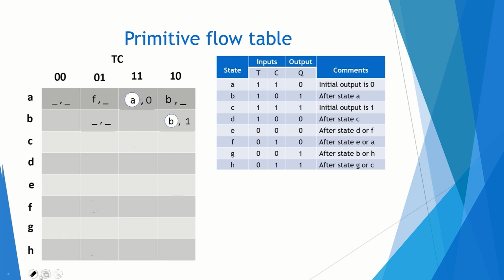So you can put dash here. So let us now see this B, that is 1 0, output 1. When it changes to 0 0, C is going from 0, so there is no triggering. So the output will be in the same state, that is 1. So it is 0 0 1.